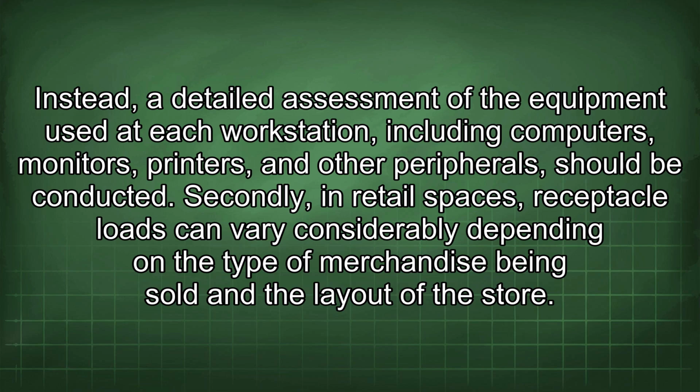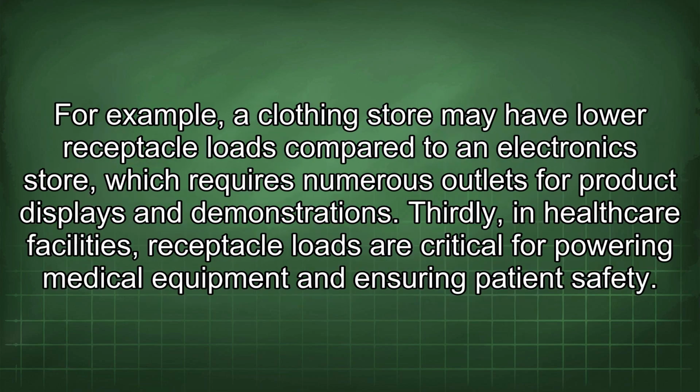should be conducted. Secondly, in retail spaces, receptacle loads can vary considerably depending on the type of merchandise being sold and the layout of the store. For example, a clothing store may have lower receptacle loads compared to an electronics store, which requires numerous outlets for product displays and demonstrations. Thirdly, in healthcare facilities, receptacle loads are critical for powering medical equipment and ensuring patient safety.